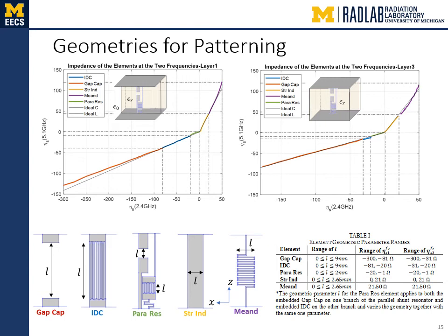Thus, after the elements were designed and characterized, the actual frequency scaling was used in the design and the stacked metasurface antenna was redesigned. We use these geometries to realize the sheet impedances in a patterned cladding stacked metasurface antenna and obtain the scattered fields through COMSOL Multiphysics simulations.